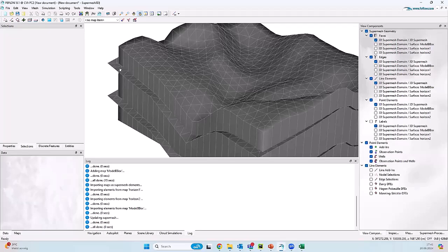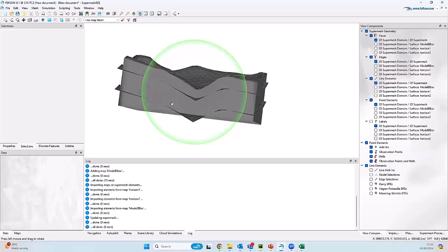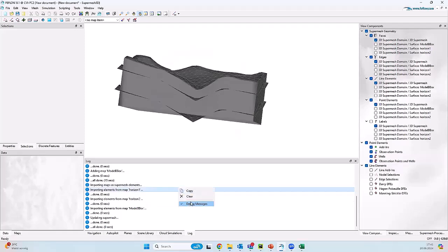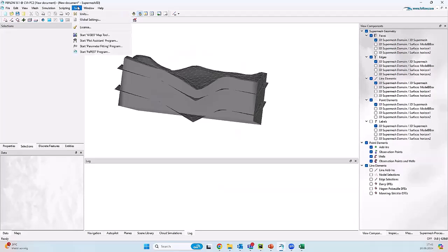and this gap will end up either in small tetrahedrons between the vertical face of the bounding box and the horizons, or in the best case, it will mesh it, but you don't get regions. You expect to see from your conceptual model 3 different layers, but since there is a tiny gap in between, FEFLOW will just recognize one single block. So that is something that you need to watch out for. I'll give you a trick here.